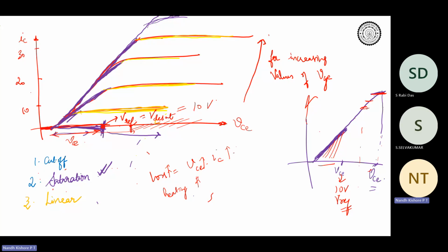If the voltage drop goes beyond a particular point, then the current saturates. So you transition from the violet region towards the yellow region, correct? In terms of nomenclature, you are leaving the saturation region for the IGBT and going towards the linear region, or what is known as the desaturation region. So the idea is that you want to sense that the device is leaving this region and going into the desaturation region, and based on that you want to take protective action.